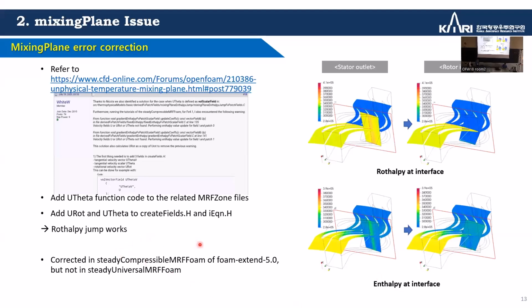And you can see that foam-extend 5.0 is a recently released new version, and here is another compressible MRF solver called CD compressible MRF foam. Here this issue was solved. I mean, the problem was corrected, but unfortunately, in CD universal MRF foam it did not change. So you should care about that also.